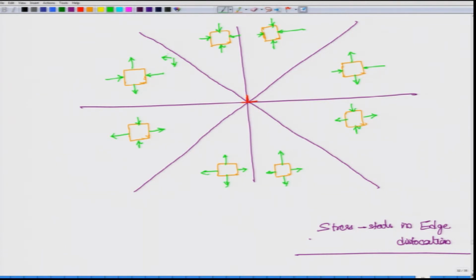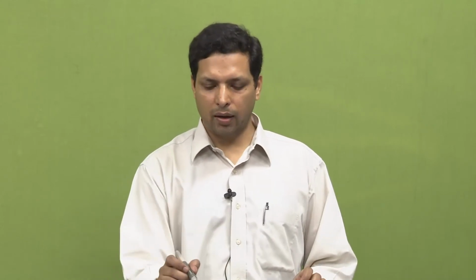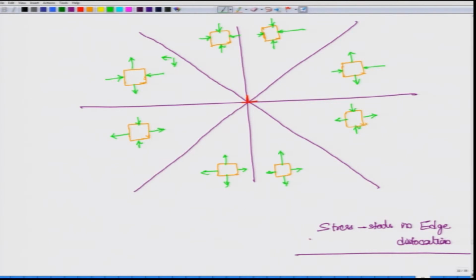Because in shear stresses there must be 2 stresses acting, so that there is a balancing between the 2 stresses. If we apply only one type of stress, then it will lead to rotation, which we know is not really taking place. So, it always occurs in pair, like we saw sigma xy and sigma yx. So, if this is sigma xy, the other one is sigma yx.